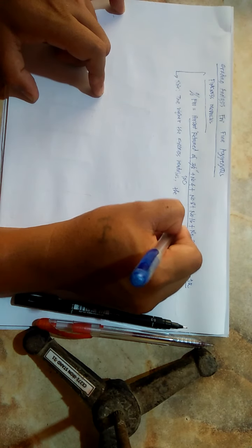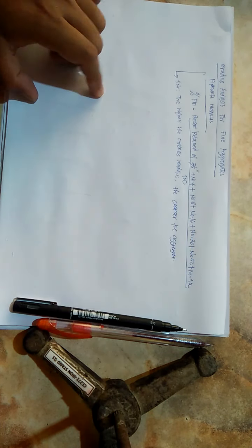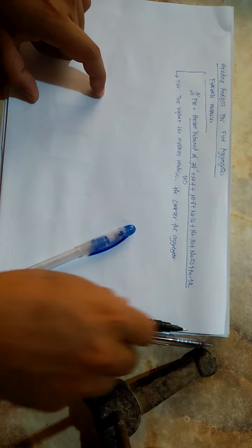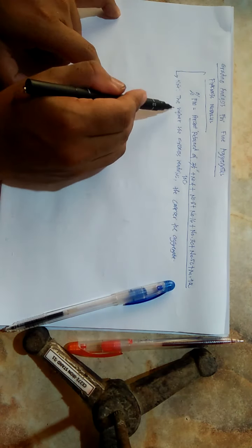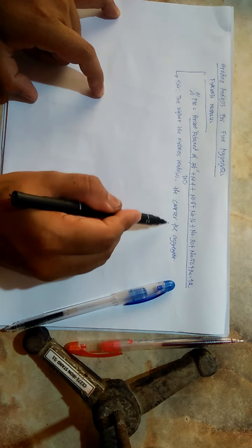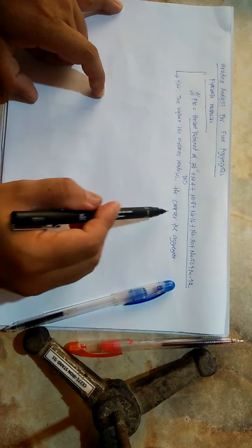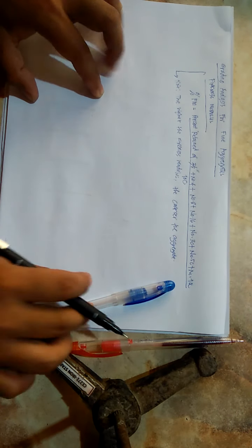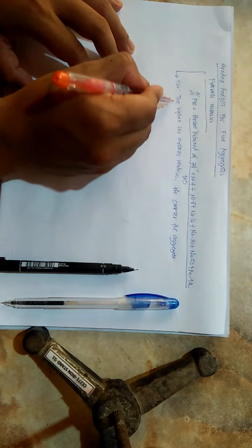Okay? That is why we need to determine your fineness modulus because of this condition that the higher the fineness modulus, the coarser the aggregate. Otherwise, the lesser the fineness modulus, the finer the aggregate. Okay? So, ito yung importance ng fineness modulus natin.